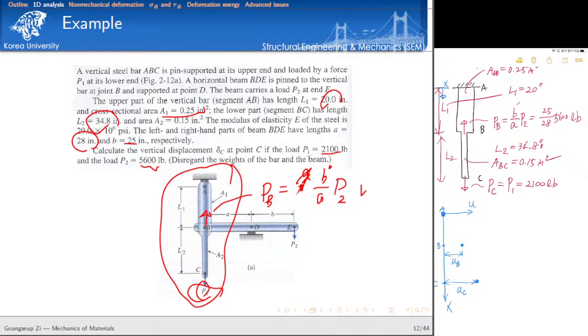The distribution of displacement field looks like this. As I told you, because we want to consider homogeneous materials, the slope is always constant. Okay? So in my map, the displacement, strain, stress, and the force. So we just identified the deformation field. So next step, we need to calculate the strain, isn't it, right? So now let's try to calculate the strain.